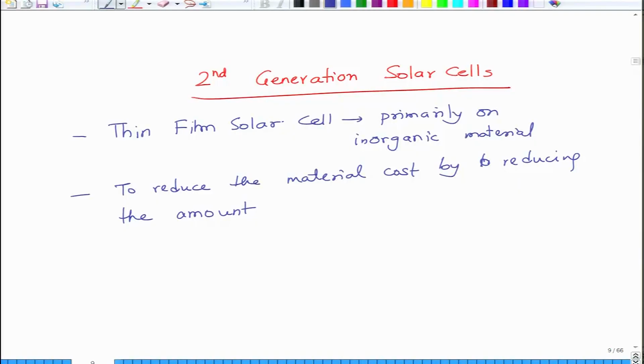Since the 80s onwards vacuum technology matured, that is why thin film technology also got superior, and that is where most of the thin film devices also got a kick, because of improvements in the vacuum technology and equipment. You could make cleaner materials in thin film form. In thin film form, the cleanliness is very important, because if a small dust particle gets in which is of the same dimension as the thin film, your thin film will be dead. So that is why you require a very clean atmosphere for thin films, and that is why vacuum is preferred over air.